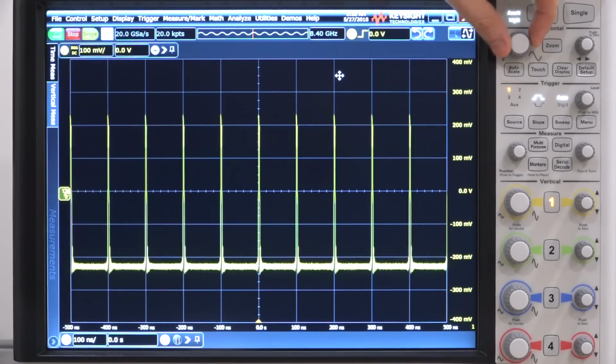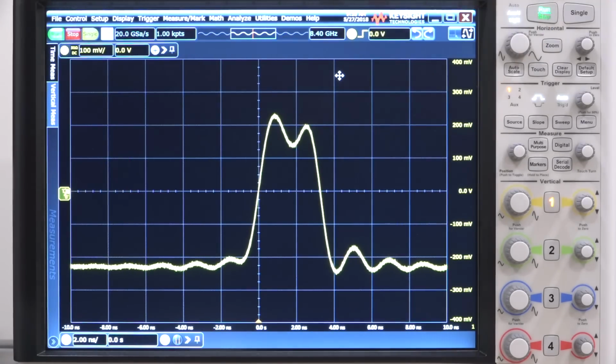So we can see one of these pulses, and check it out, there's one of the pulses, and it's kind of moving around. This has to do with a likely problem with the way the data is generated, and the data has a rolling effect with respect to the clock rate. That's why you're getting this overall moving effect, as the data going into the DAC is not exactly repeated every cycle. And this is of course a problem. You don't want this to do this.